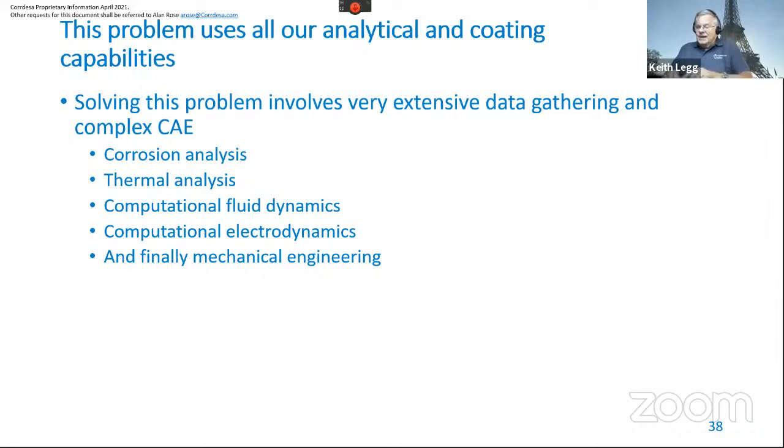Then you make a new mask outside that, and now you've got an overlap area and you've defined the area that you're coating. That's the best way to solve the problem. For the floor anodizing, the areas are really not that well defined, so you don't have to get it super accurate. We think we can actually get away without masking, which saves time and trouble. But you do have to overlap.